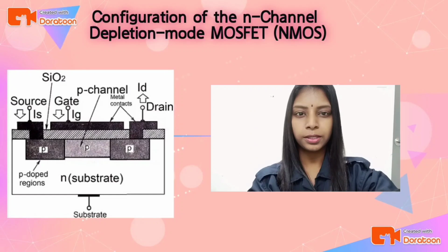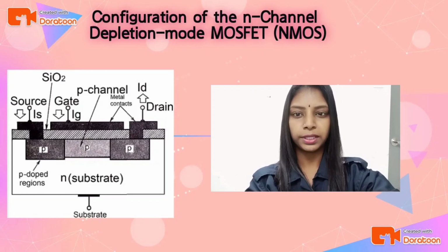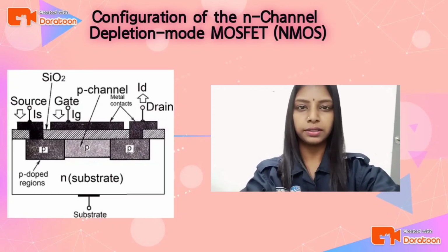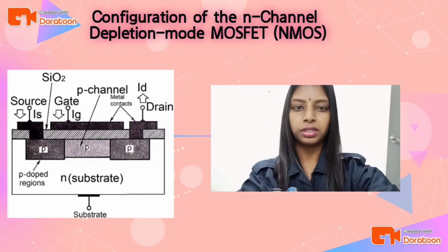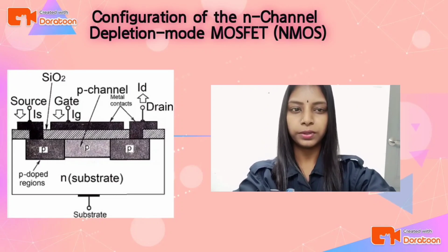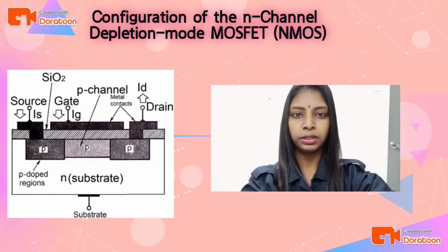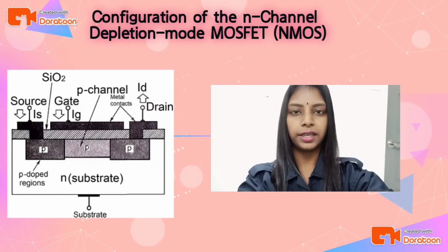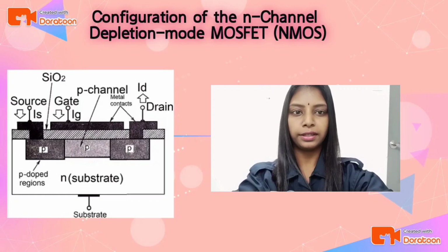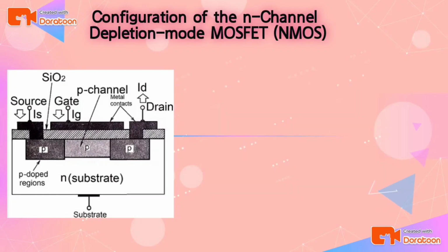The gate terminal is isolated from the channel using the SiO2 layer. So, if you see the structure of this MOSFET, it consists of metallic contacts for the drain, gate and the source terminals, the insulating layer, and the channel, which is made up of the semiconductor material. That's why this MOSFET is known as metal oxide semiconductor field effect transistor. Due to this insulating layer, there will be no flow of current through the gate terminal. The input impedance of the gate terminal is very high, and in fact it is even higher than the JFETs.